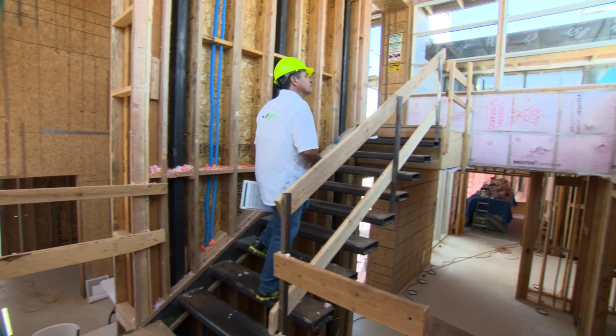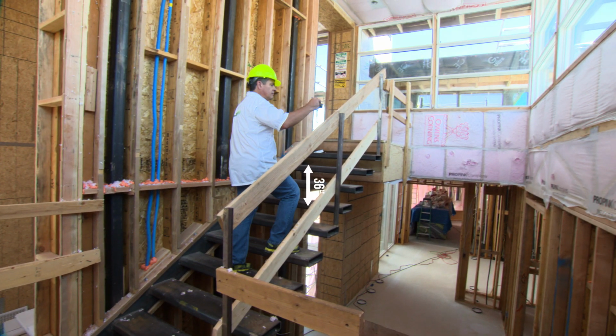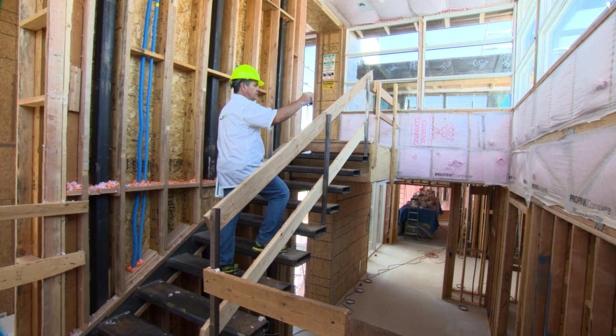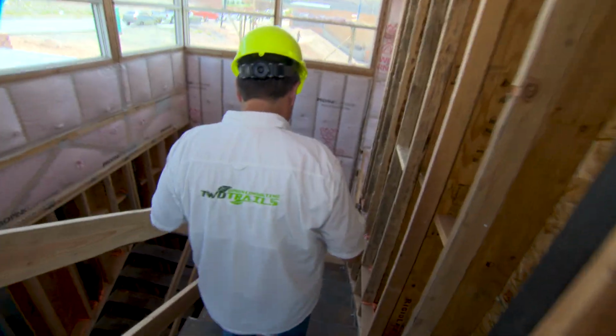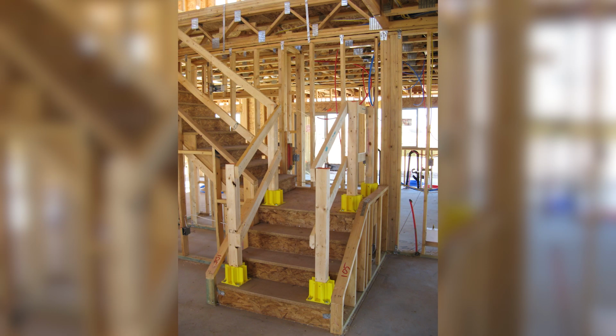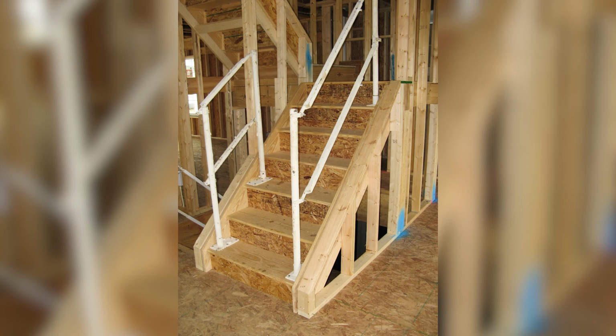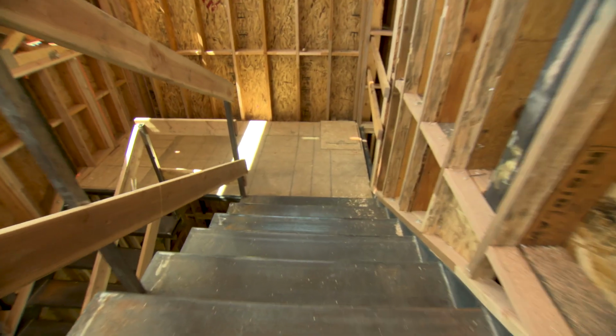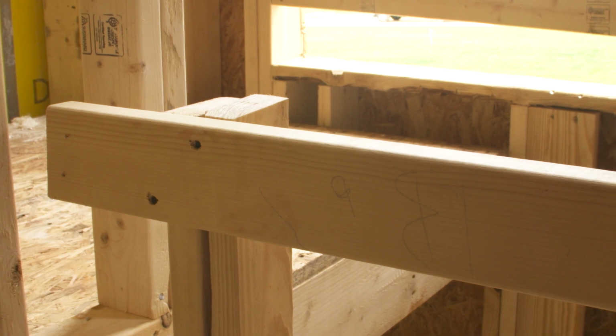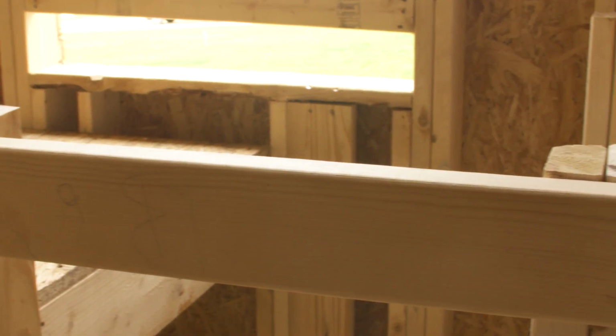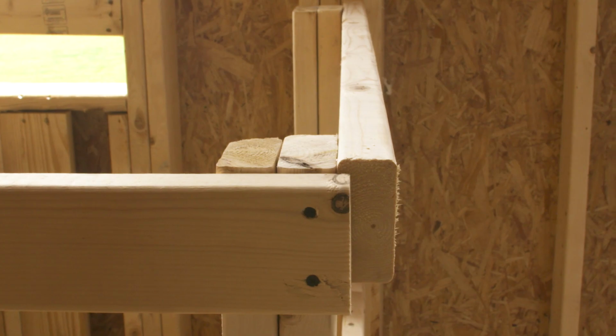Install stair rails at 36 inches from the top of the stair rail to the front edge of the riser, so it can serve as both stair and handrail, and install mid-rails halfway between the stair rail and the stair stringer. Just like other guardrails, build the stair rail system strong enough to withstand 200 pounds of force applied in any direction along the rail. And again, make sure the rail is not surfaced to create any injury hazards, such as protruding nails or sharp edges that may puncture or lacerate hands, as well as snag clothing.